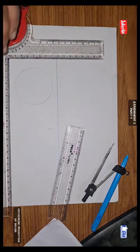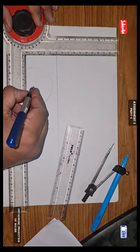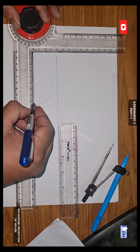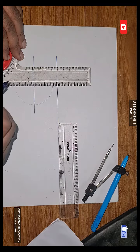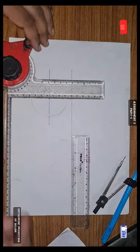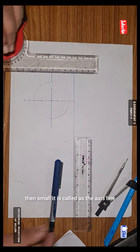Make a circle like this, and then you need to make a central axis like this. This line should be a long line, then a small dash will be there. Then a long line, then small dash, then long, then small. It is called the axis line.